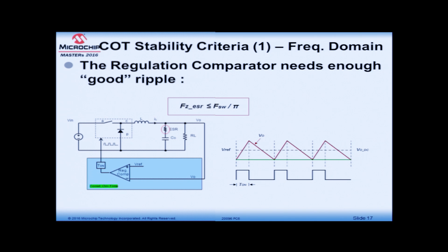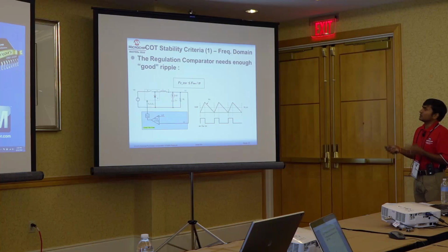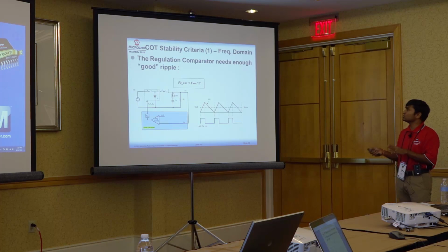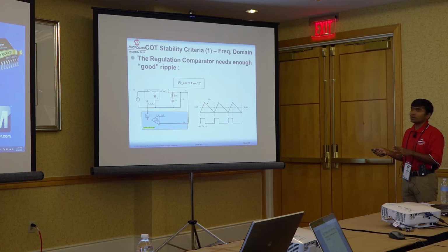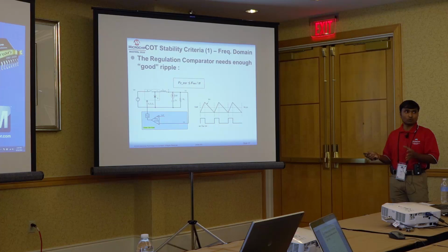Generally it is 30%, and the output capacitor is selected based on how much steady state ripple and transient ripple we can allow at the output, and the switches are selected based on the input voltage rating and also the RMS current that goes through them. But we will concentrate mostly on the control portion of it, how to design the control system to work with the